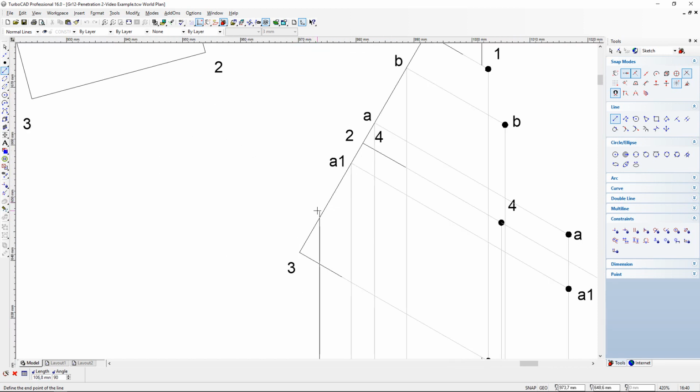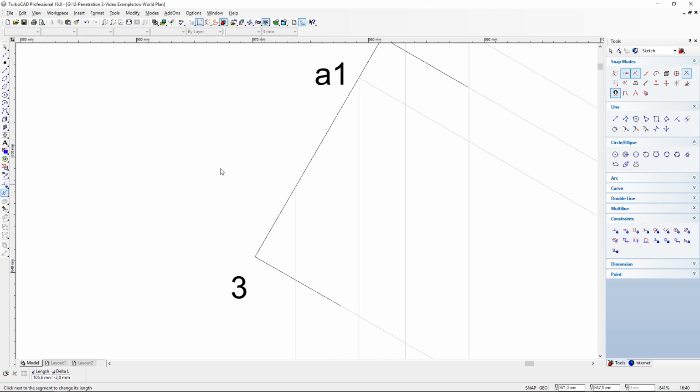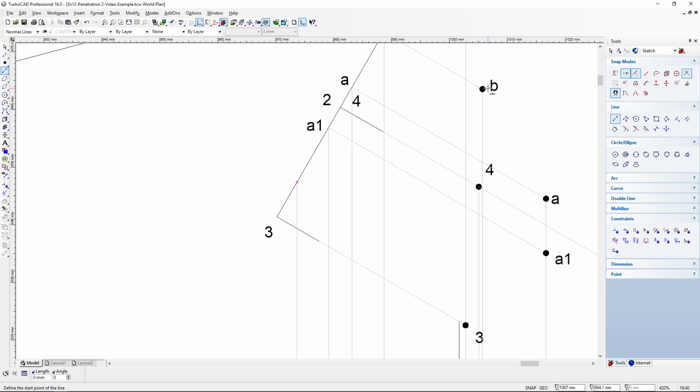Now we need to do that here at the front view, and then draw the line right to the edge. And again, we already have now the depth of B1 because it's the same as the depth of B. And we're going to take that intersection and then draw a light construction line at the angle of negative 30 or 330 degrees.